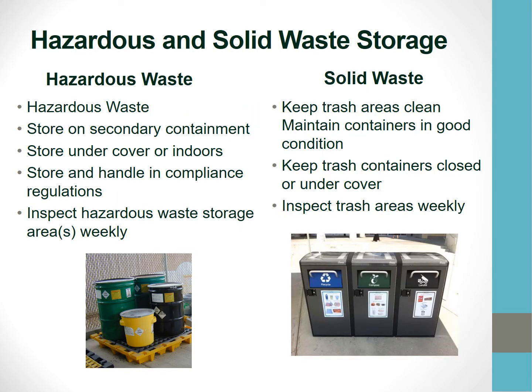It is important to manage hazardous and solid waste properly. Hazardous waste should be stored on secondary containment off the ground. The waste should be stored under covers or indoors. Store and handle in compliance with hazardous waste regulations and inspect hazardous waste storage areas weekly.